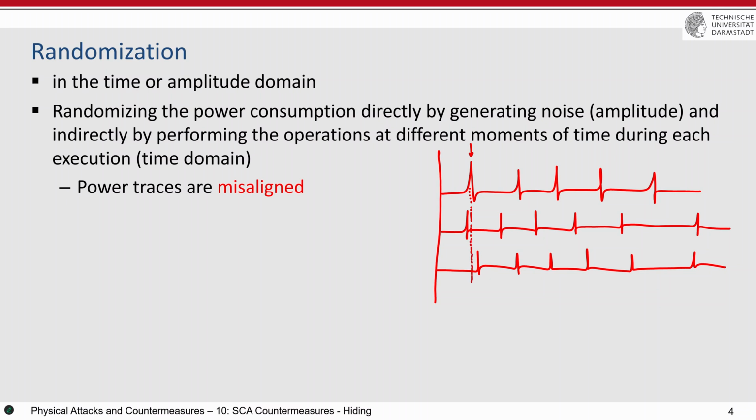Of course, if you run the attack just like this, then you need many more traces to perform the attack, because this just makes the attacks harder. I mean, they do not prevent the attack. Because anyway, if you increase the number of traces, there will be some traces that have the peak at exactly the same point in time, and then it will be aligned. The solution for that is to detect the peaks for every trace, and then make, for example, a window over this, for example 50 points before and 50 points after, and the same for each of them.